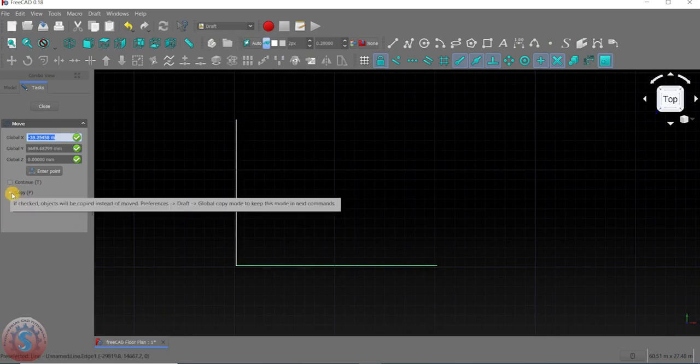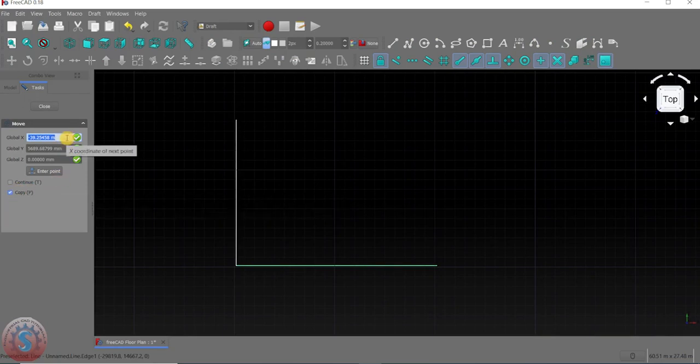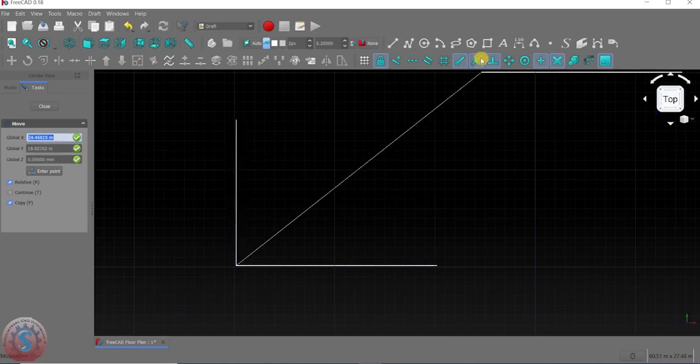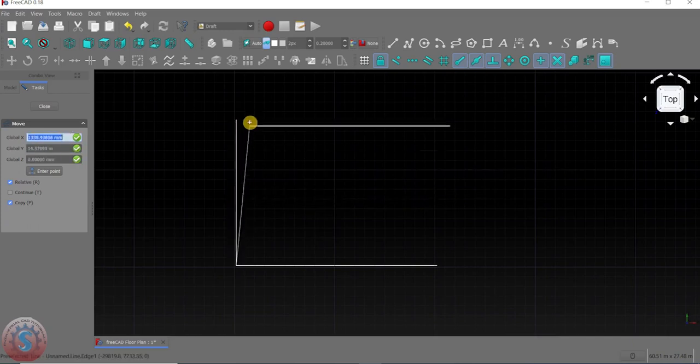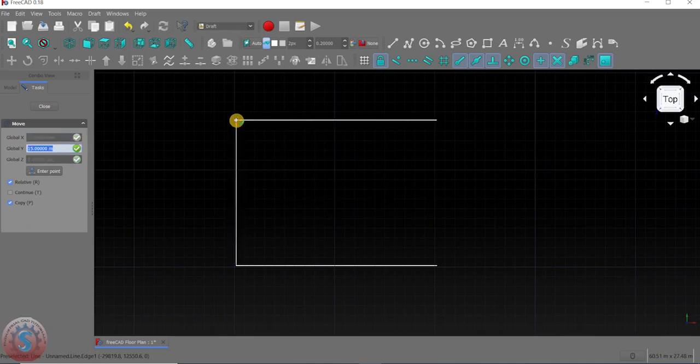Click on the copy option here and check this option. It requires which direction you want to copy this object. For example, I'm copying and moving the object. You can observe the midpoint is highlighting because this is the midpoint we enabled in the options. If all the points are enabled, all are highlighting. I want to move this same line to the top of the endpoint. For example, I'm giving the copy. If you do not press the copy option, it does not form the line here.